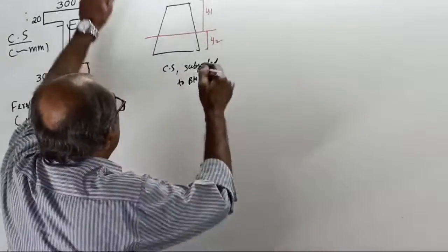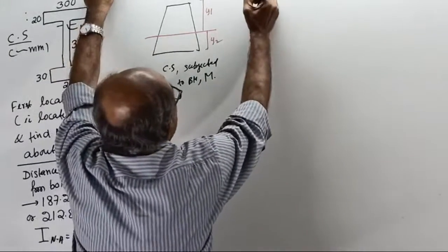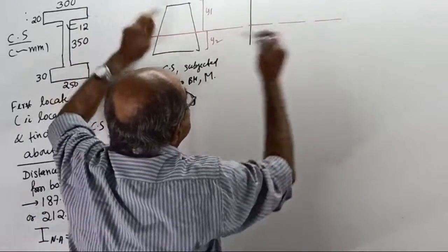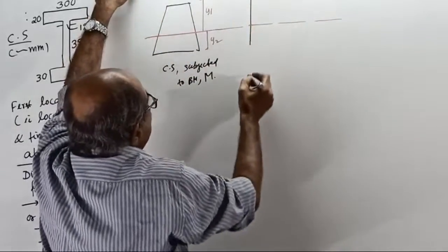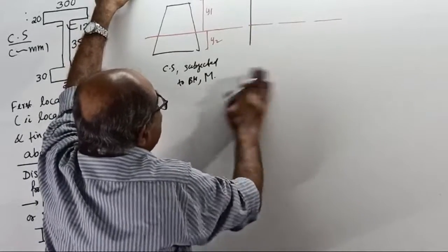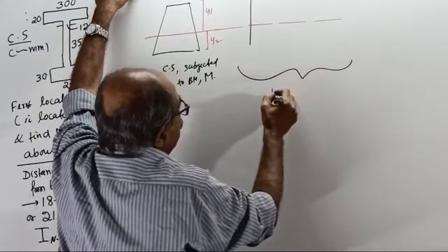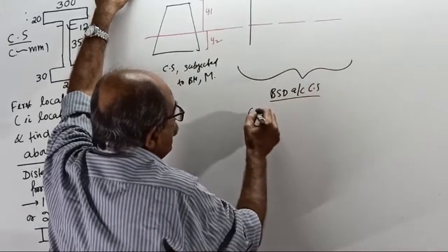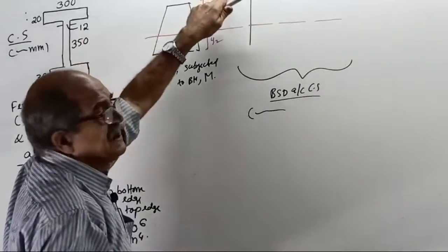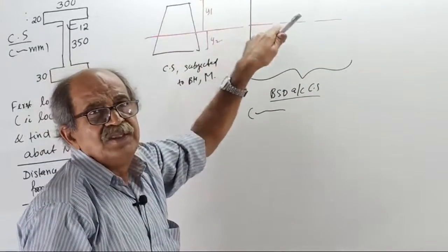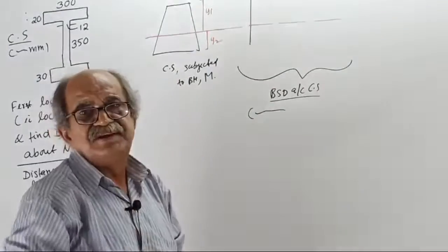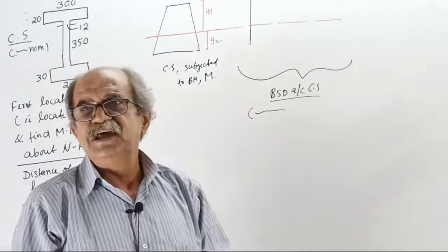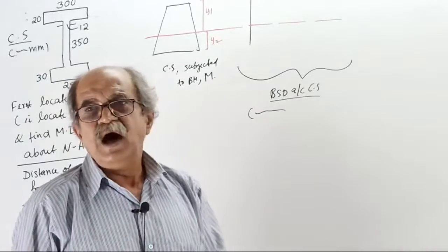Now I will explain as last time. Bending stress distribution, this is the neutral axis. Now, what I am writing here is the bending stress distribution across the cross-section. You can write it if you want. Maximum at the extreme fiber, 0 at the neutral axis, linear variation. One side compression, one side tension. Those who are serious will write it. So I am not writing it now.